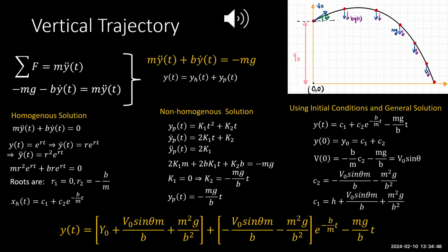However, as shown for the next part, the vertical trajectory, it's much more difficult to ascertain because initially your object is flying upward in the air, meaning the drag is pushing down on it. After a certain peak, when the object starts to go down, the drag is pushing up on the object. Mathematically this is still okay, because if you have directional velocity and your drag is negative in that direction, it equals out. You just have to know that at a certain peak it's going to change directions, and that can make simulating things much more difficult.